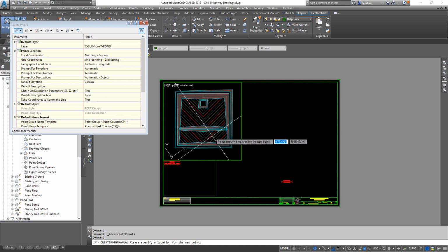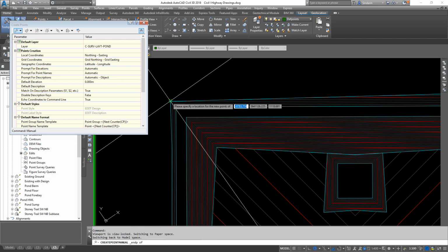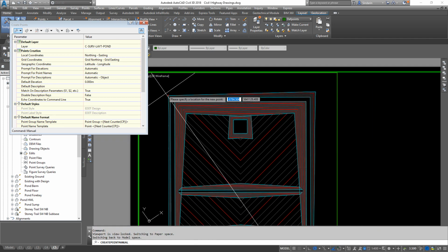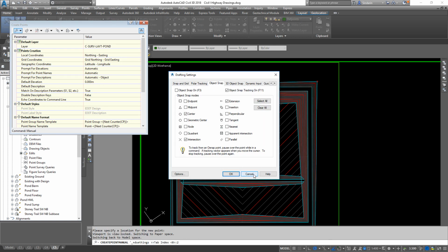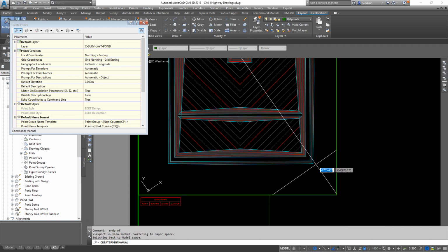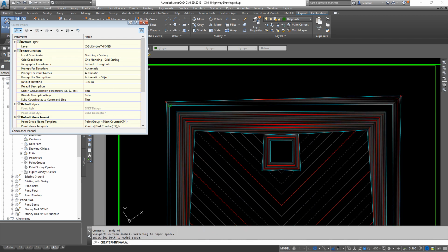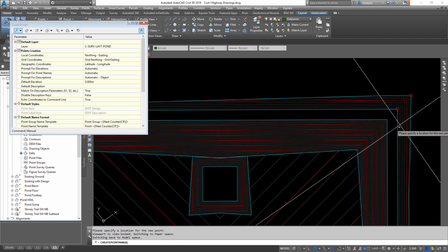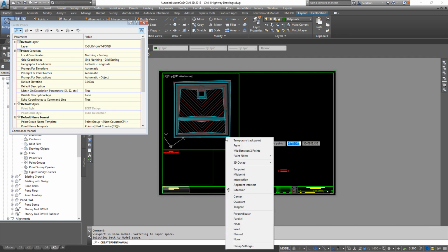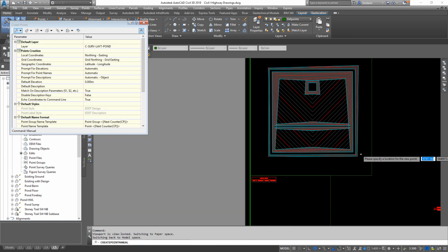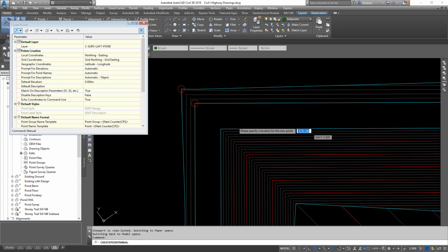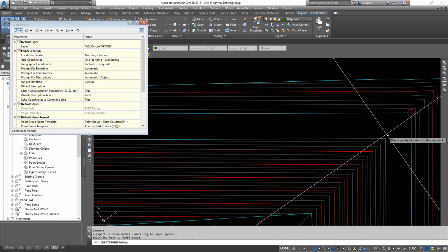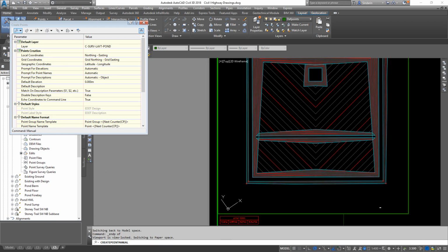Now when I create these layout points, I'm going to go in a logical order. So I'm going to snap to the endpoints of items. So the endpoints of my outside berms, and then I'm going to go on the insides of my berms. And again, make sure you're snapping to the endpoints. Endpoint down here, endpoint down here. And I'm just going to continue working around the outside.